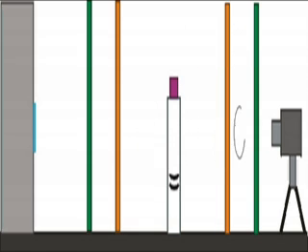A clear transparent solid such as glass is inserted into the light path between the quarter wave plates. When stresses in the glass are set up by a mechanical disturbance such as our ultrasonic pulse, it causes a change in the rotation of the polarized light. Changes in stress along the light path change the conditions that nulled the light passing through the analyzer, so a small amount of light can then pass to an observer on the other side of the analyzer. By adding a delay circuit, we can adjust the position along the sound path that is illuminated by the pulse, and the camera allows the observer to record the image.